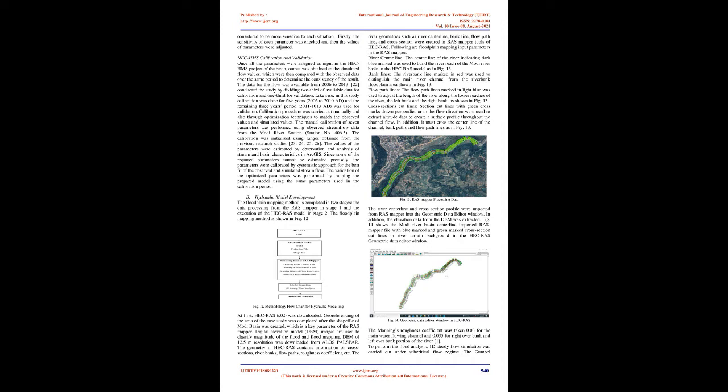Basin processing. The batch point was created at the outlet of the catchment and the watershed was delineated. The resulting catchment area for the Modi River Basin was 676.034 square kilometers. The HEC-GeoHMS project setup menu was completed by defining two feature classes, project point and project area. For the sub-basin and river, physical characteristics were calculated based on the refined DEM.